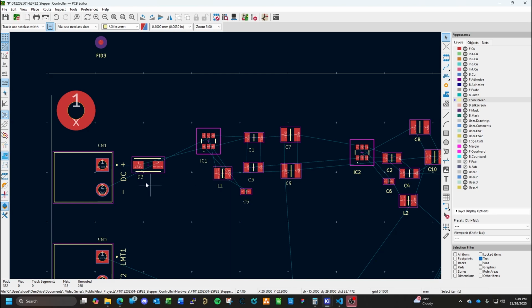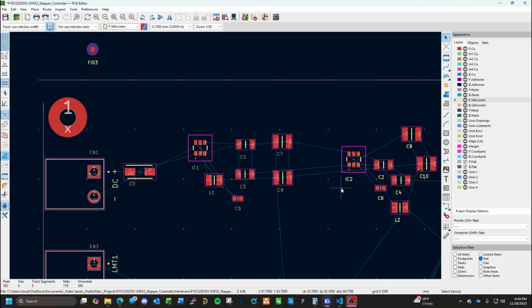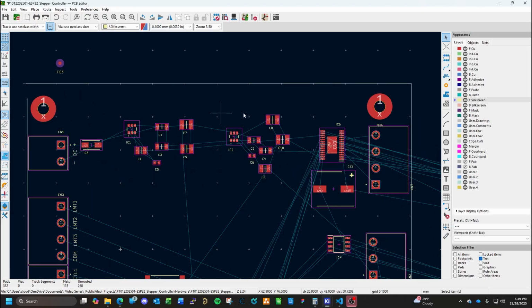So we know there's our 24 volt coming in. We'll consider it coming up here as the main 24 volt rail. That way you can come up here and go straight to the motor controller and feed the two power supplies. Basically a bus, the 24 volt bus. It's not an individual plane. It's connected. It's there. And we don't have to worry about any of it.